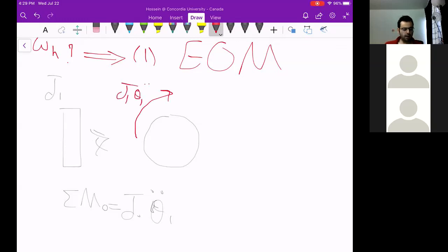So if I rotate the left disk, what kind of torque will oppose the motion? There is a spring, right? Yes, there's a spring, so minus K equivalent, because there's a restoring torque. Since the equivalent torsional stiffness is attached between the left and right disc, the total torsional deflection depends on the rotation of the two discs.